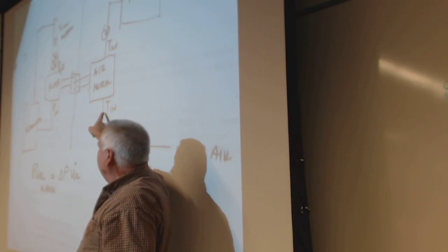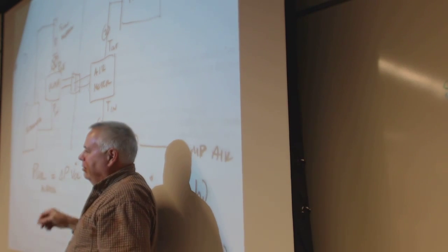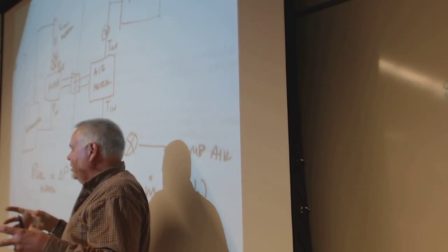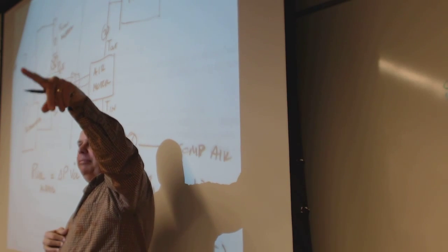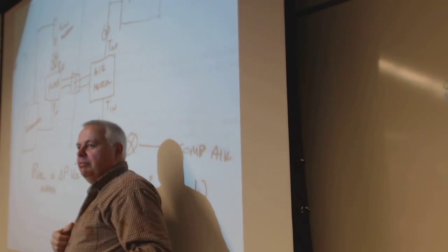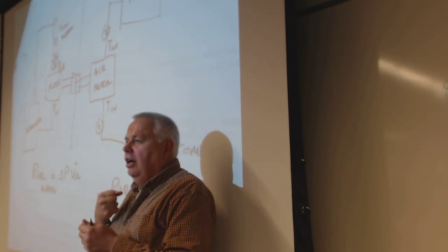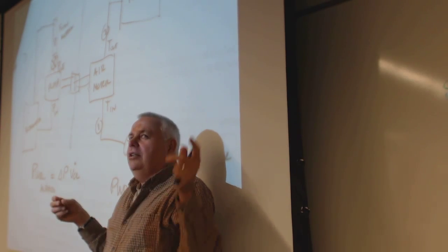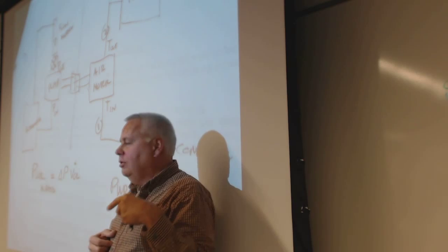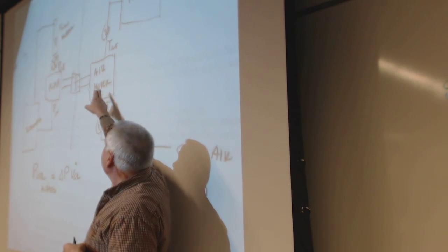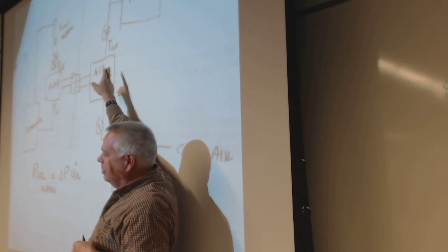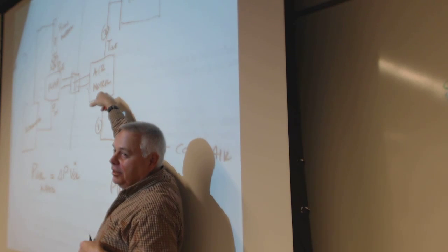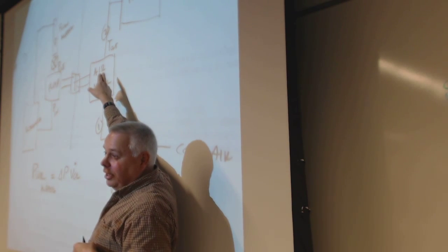The funny thing about air motors, on the way in, when the air was initially compressed, it went into the tank, wherever the tank is in this building. It's piped all over the building. We have a drop right there for compressed air. But it went into the tank hot, and then it cooled down to room temperature. And then it comes through the pipes, and the pipes are all at room temperature. It comes to your place here at room temperature, then it expands. What do you suppose the temperature on the outside is going to be? It's going to be hotter than it went in. If it's hotter, it means it gains some energy, right?